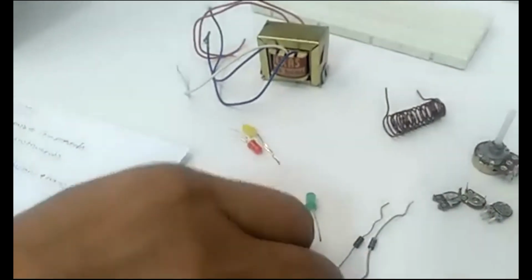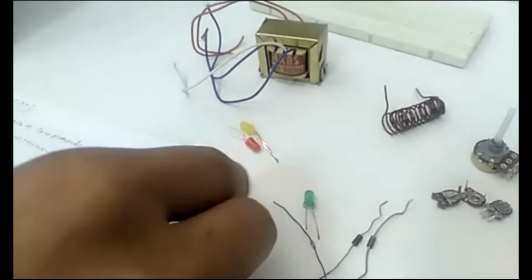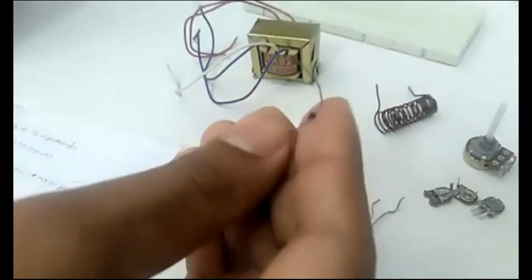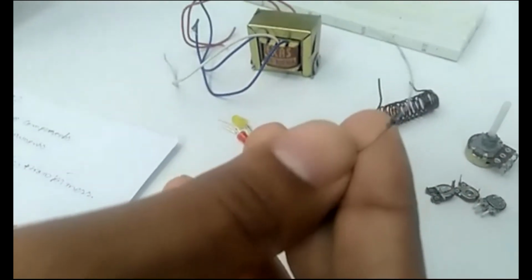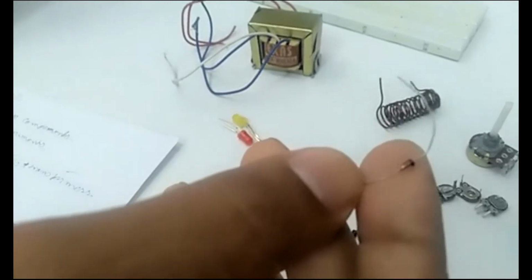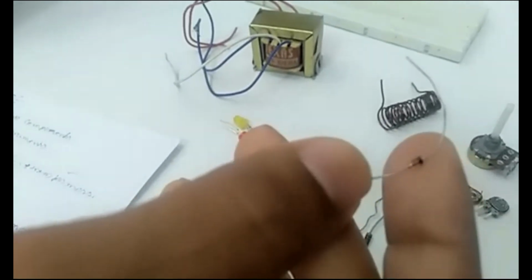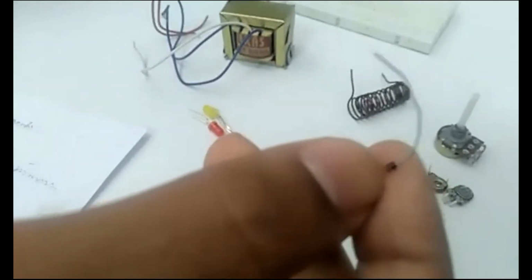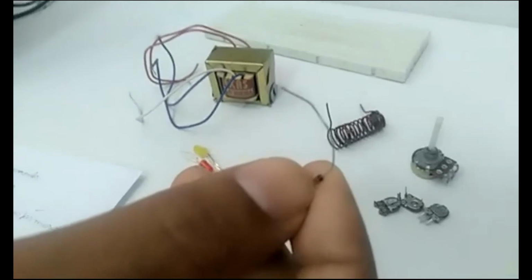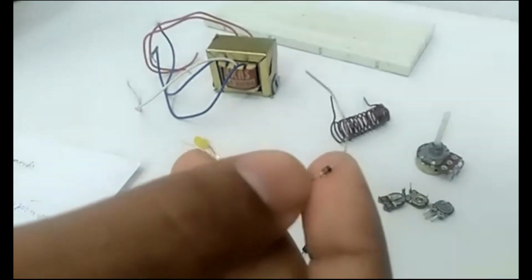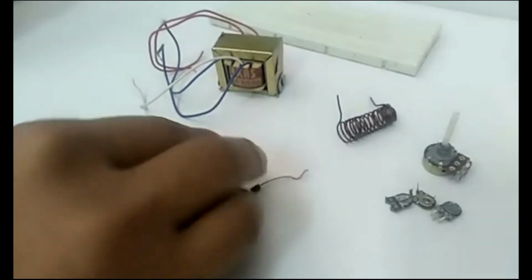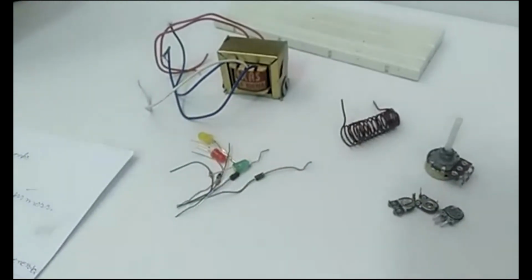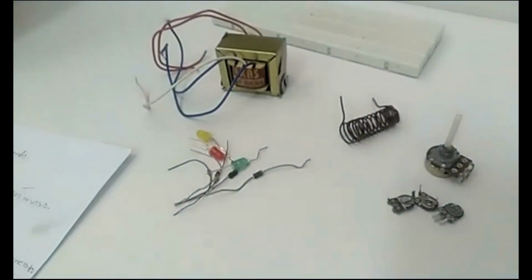Here, if you observe, these are Zener diodes, another special purpose diode. We are going to use those for different experiments too, specifically a Zener diode experiment. In order to distinguish the two electrode terminals, there is also a black coating, and that is the N terminal. So you can connect the P terminal and N terminal in this way. These are basically the different types of diodes we have in the lab.